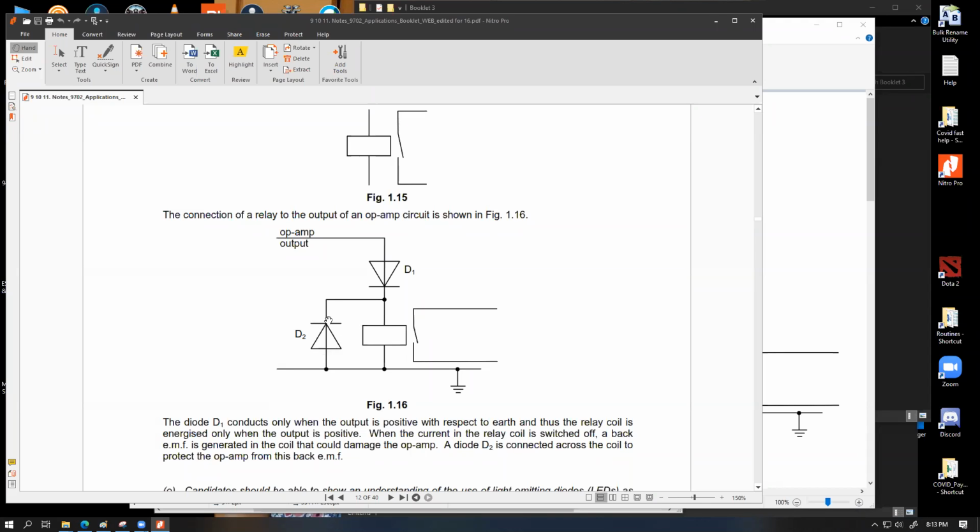The purpose of the D2 diode is to stop the current that was originally coming from diode 1 from bypassing through a single piece of wire to the ground, so that that current would be pushed through the solenoid. D2 performs not when the back EMF is activated. D2 performs its blocking purpose when the solenoid is actually working, when the op-amp output is actually positive. The diode over here is required so that the current that is naturally flowing through this thing, when this external circuit is working, has to flow through the solenoid. It does not get bypassed through this path. But for the current to flow through this pathway, a single piece of wire would be good enough. But if we do provide a single piece of wire, then this current would be simply bypassed through here. It would not flow through the solenoid. So D2 basically serves this purpose when the op-amp is providing its basic current.